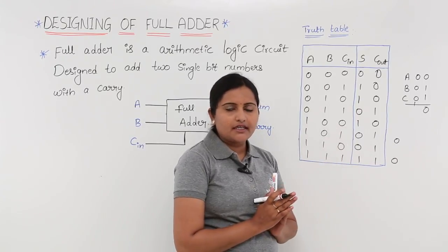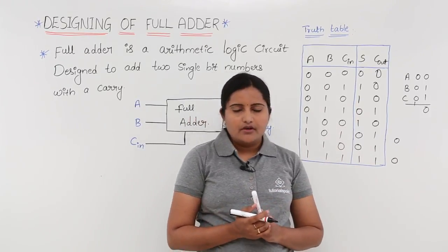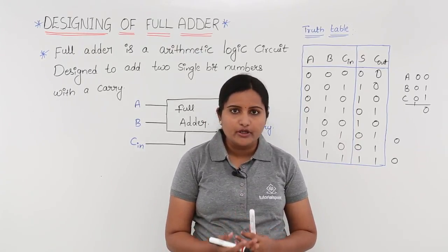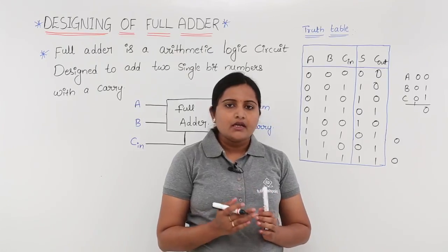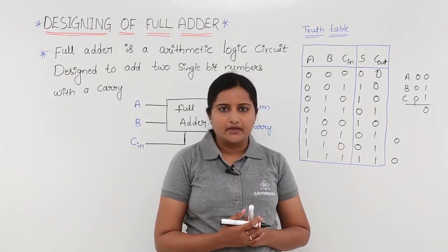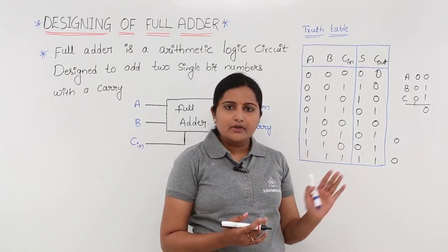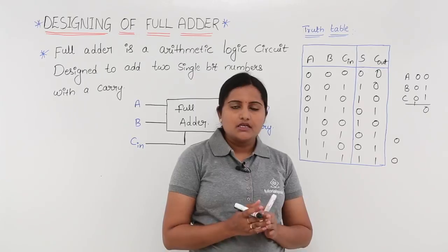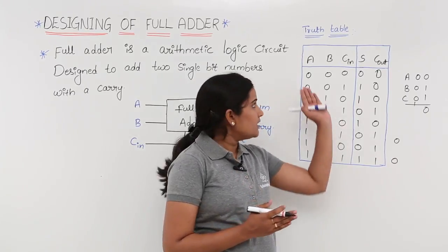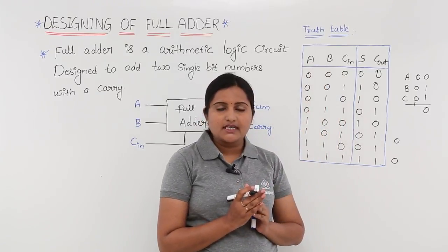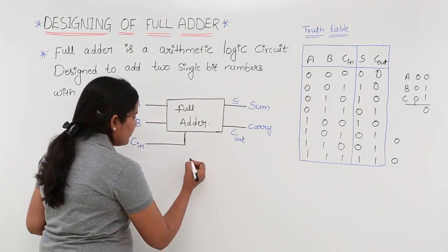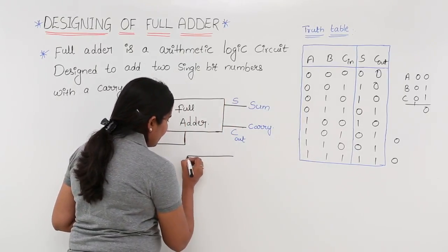For this functionality you need to design the logic circuit. First of all, to design any logic circuit you need a logical expression or Boolean expression for that relation. Here to derive any Boolean expression you are making use of a K-map. Now how many variable K-map do we need to consider? I am going to consider a 3 variable K-map, because here we are having 3 input variables, that is why I am going to use a 3 variable K-map.